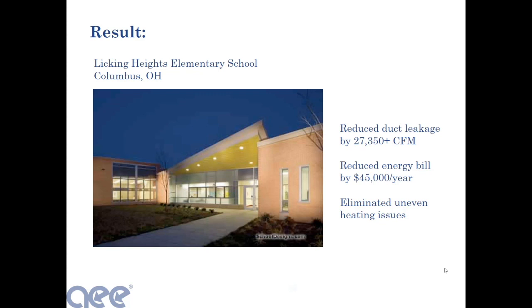The problem with this particular school is it was identical footprint, identical location, 30% higher energy consumption than its sister school. In fact, they had two 40 horsepower fan motors that ran 24/7, 365, no setbacks. And so the school district asked the obvious question, why is the energy consumption in this school so much higher than its sister school? They called in an engineer. The engineer did an evaluation. You know what they found? They found that air ducts were leaking.